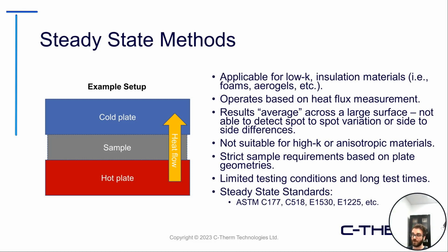Steady state methods will always take longer to perform the measurement than a transient option would. But again, steady state lends itself well to these insulation sample types, depending on what you're looking to measure, and some of the standards to maybe look out for: ASTM C177, C518. Those are among some of the more popular ones in industry.